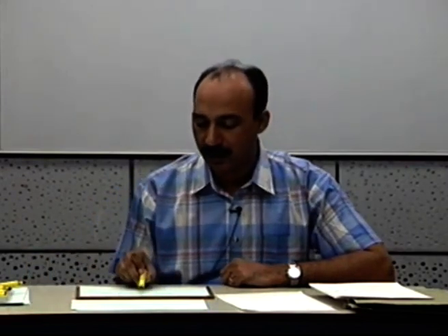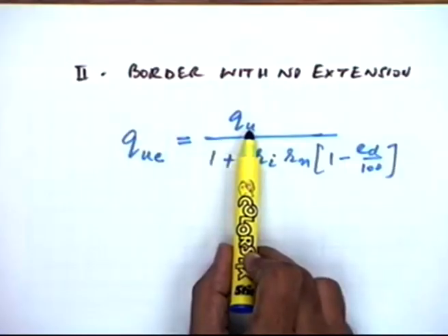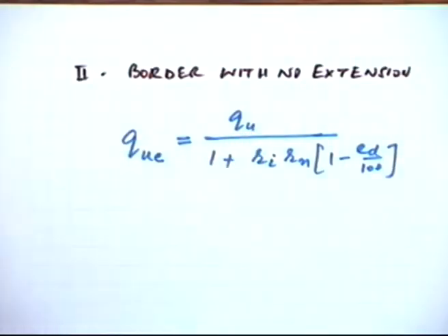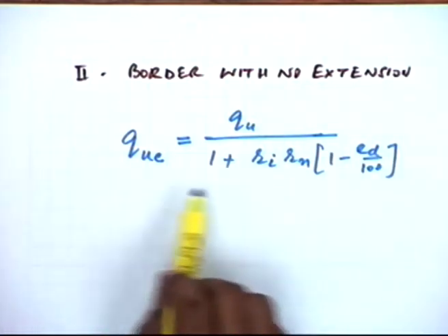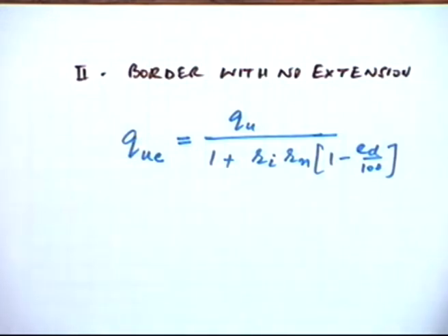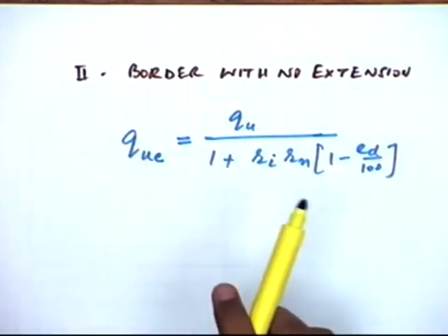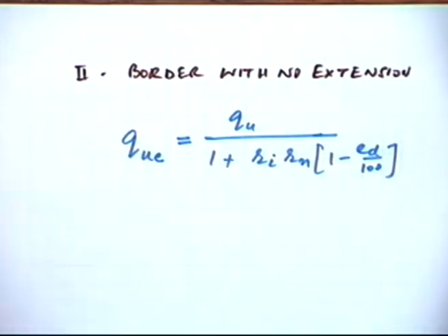We assume that due to the reduction in the stream size, the lag time is not appreciably changed. We are using the same lag time, and with that assumption we are finding out what is the reduced stream size which you can use to account for the surplus runoff which was earlier available, and you are trying to accommodate that, you are trying to save that.